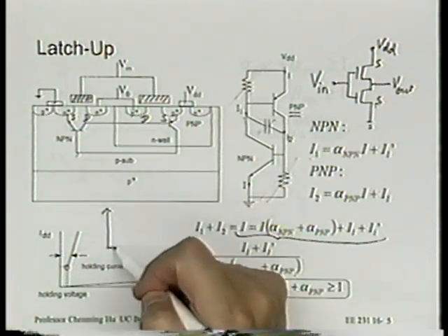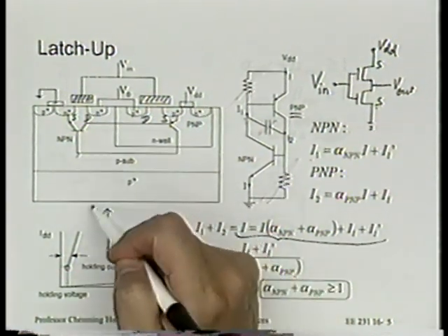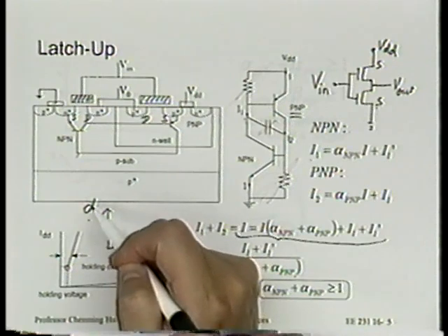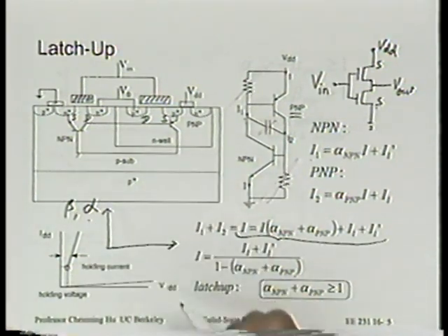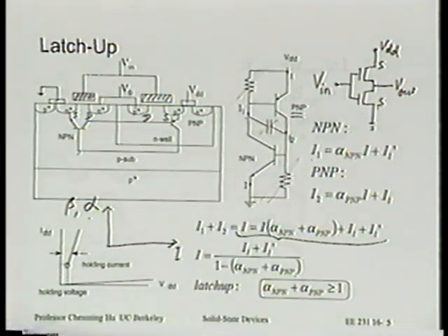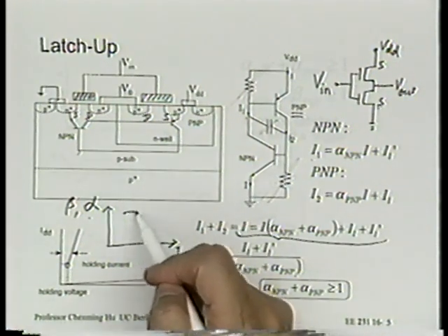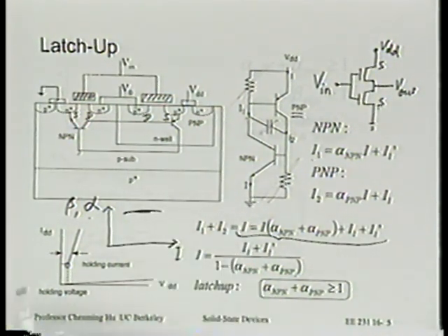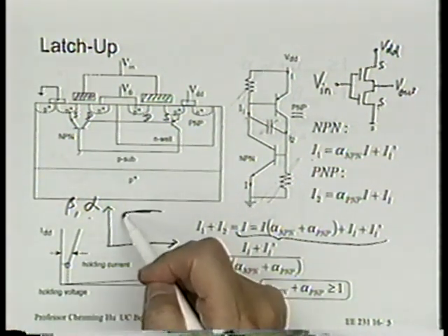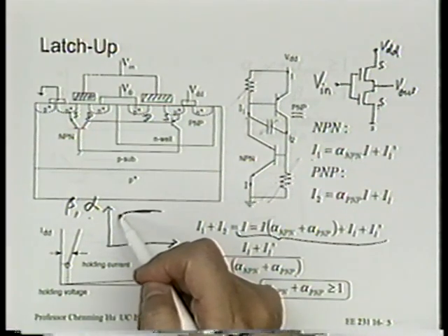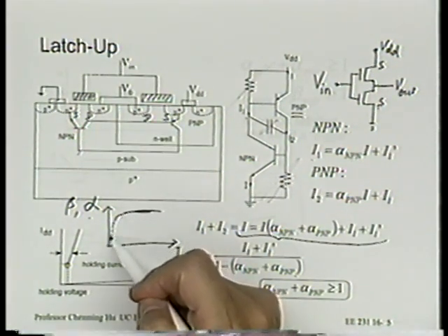The alphas, or actually betas, of a transistor are functions of the bipolar transistor current. You may remember a curve like this from somewhere. When we say 0.99, we really mean here. There's a wide range of current in which this bipolar transistor works very well. But if you look at very small current, let's say nanoamp or even picoamp, the gain drops rapidly.